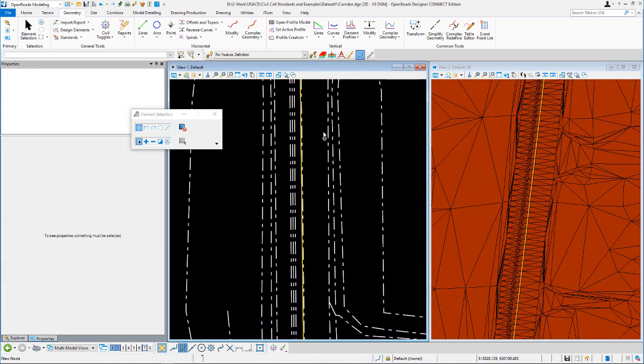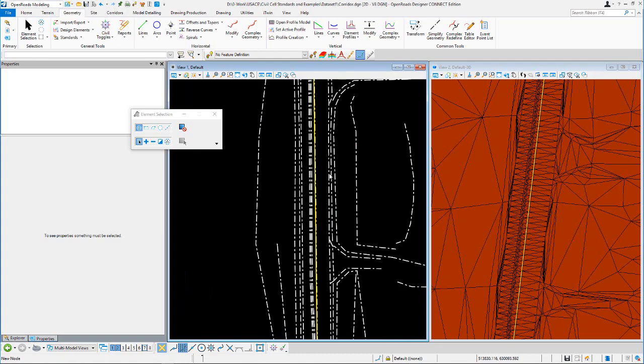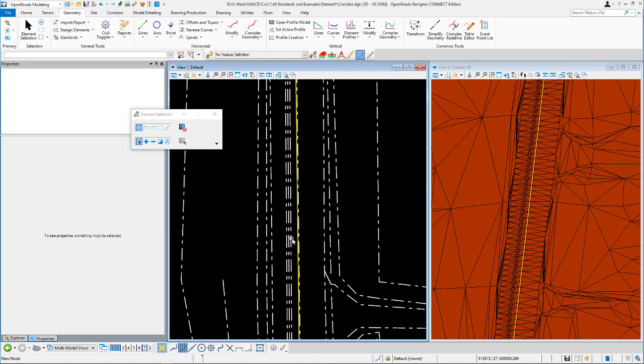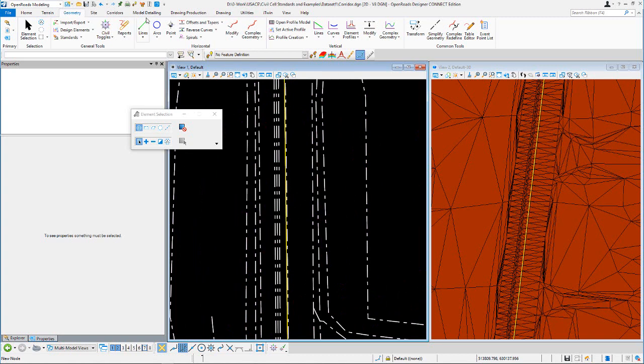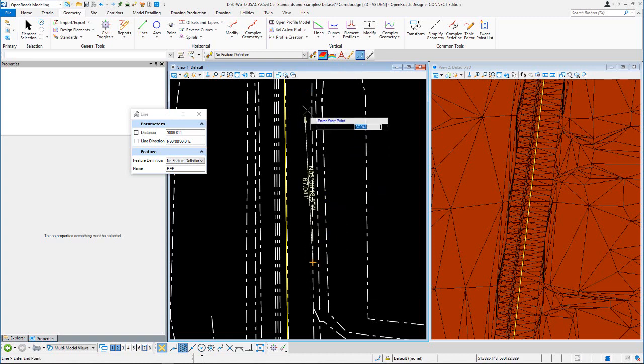And really what I'm doing, I'm just going to place a line right there, say if I want an entry right in this area right here. So I'm going to come in and just choose place line. I'm going to just call this ref. I'm going to turn on the create 3D automatically. And then really I'm going to just come in and snap to that and to that.